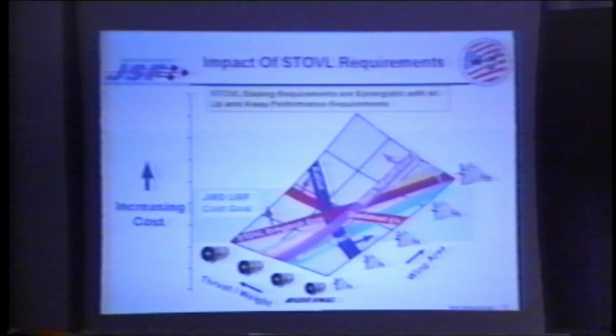Now we add some of the unique STOVL basing mode requirements. You can see in purple here short takeoff capability, which again generally improves as we increase thrust to weight of the airplane. You can also see STOVL bring back or vertical landing capability, which also improves as we increase the engine size.